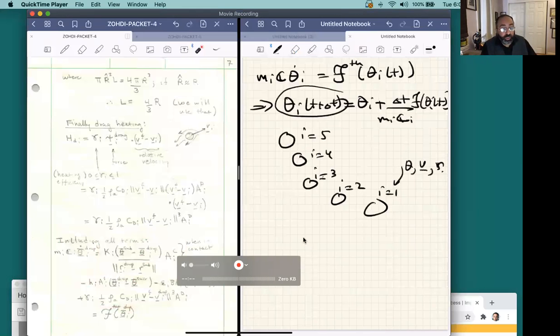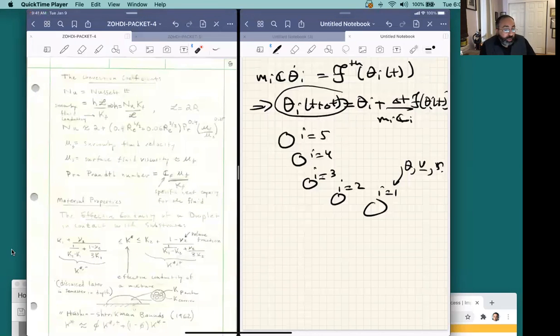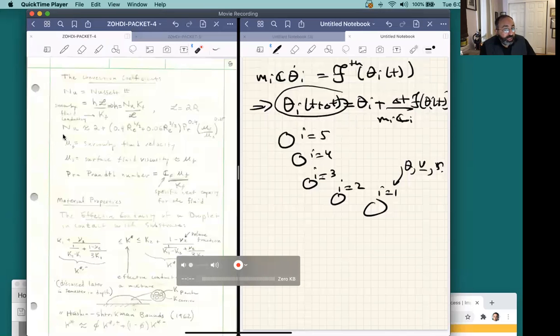So in summary, what do we do with the thing we just generated here? Well, we use this then in conjunction with many other empirical relationships. So for example, depending upon how sophisticated we want to get, we can start to describe the fluid action as a function of the Reynolds number and something called the Nusselt number. That tells us how much energy gets convected away. I leave that up to you to look at that empirical relationship. It's a hokey, funky little relationship that really is just simply a holdover from the 1950s, 60s, and 70s, although it is used continuously in the literature.